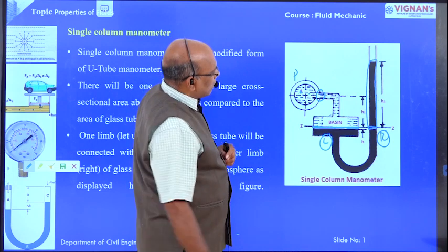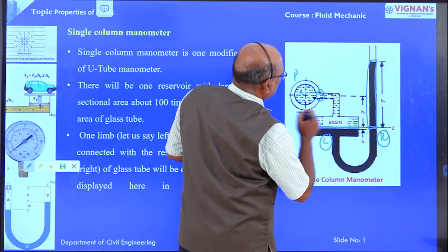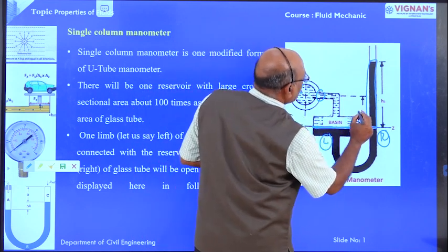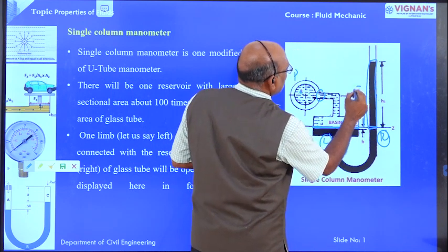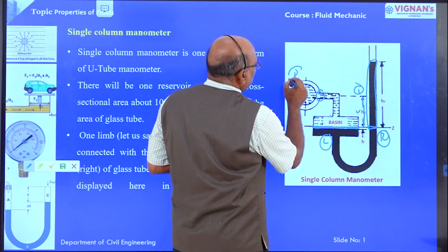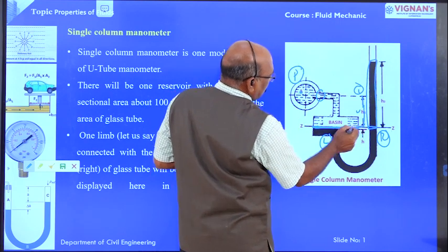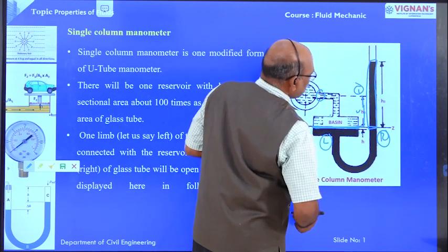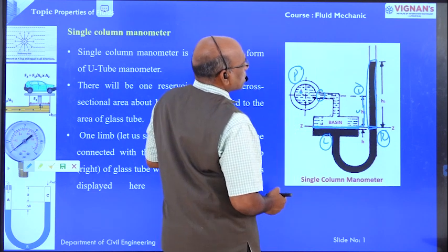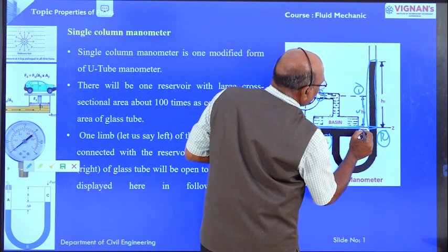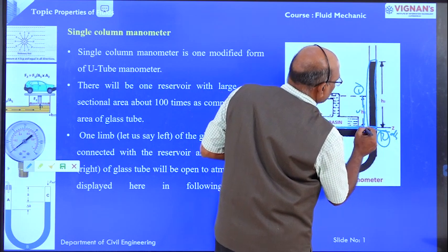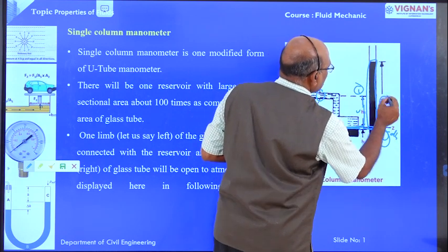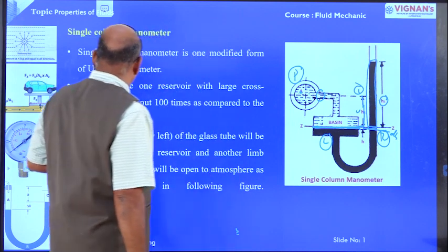One pressure is because of the water column H1. This is the one pressure in the left side, and one more pressure because of the pressure at point B. Two pressures in the left side. Right side pressures: one is because of this delta H, that is a very small variation, and another pressure because of the H2.